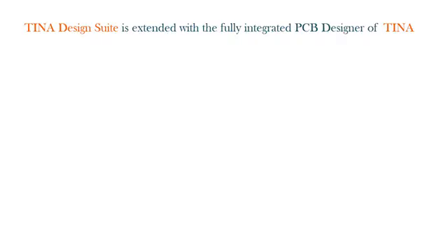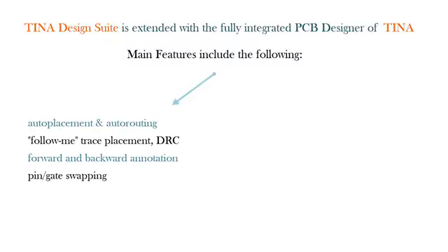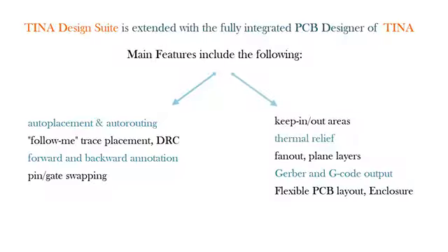TINA Design Suite is extended with the fully integrated PCB designer of TINA. Main features include the following: auto placement and auto routing, follow me trace placement, DRC, forward and backward annotation, pin and gate swapping, keep in and out areas, thermal relief, fan-out, plane layers, Gerber and G-code output, flexible PCB layout, enclosure, and more.